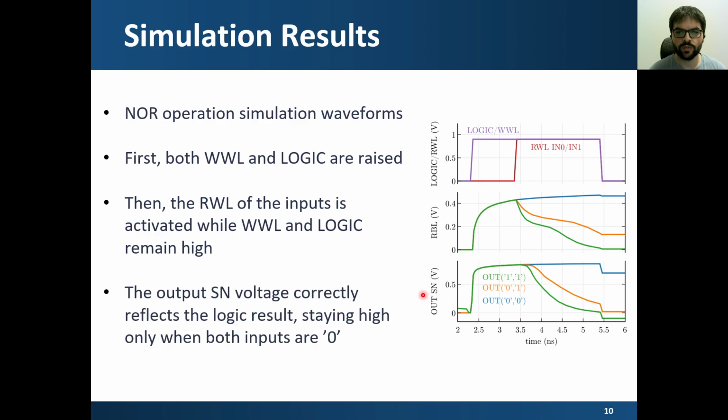If we look at the output storage node, the result, then we see that in the case both inputs were storing 0, the storage node did not change. It remained high. And in the other cases, the storage node discharged and it changed to 0 as we wanted to implement the NOR operation.